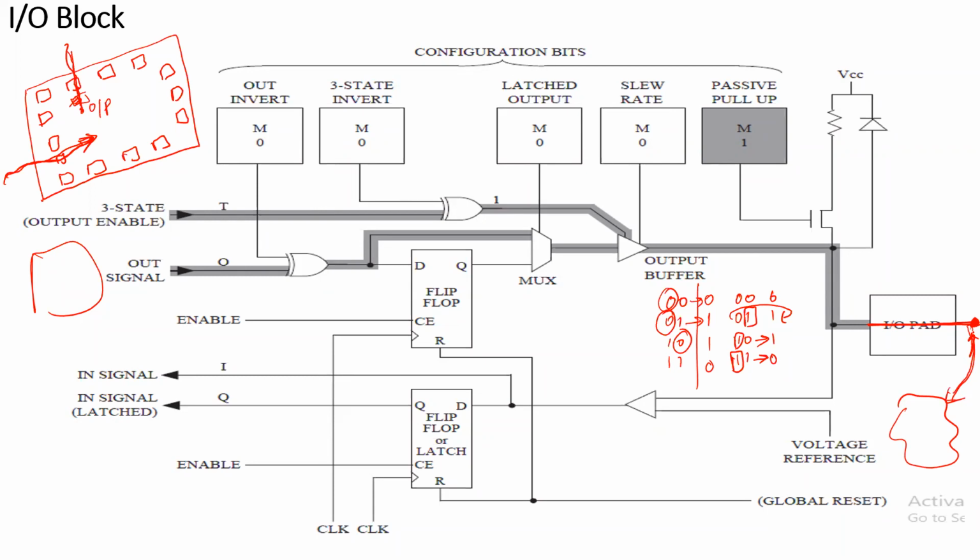So it cannot activate the other input signals, or if the speed of change of the output signal is very high, then it's very difficult to monitor that output, and it is not useful to the external world. Therefore we have to control the rate at which the output is generated, which is defined by the slew rate. By using the slew rate, we are able to control the changes of the output variable when it is connected to the external device, right?